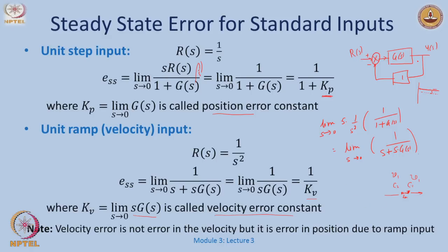Similarly, if I say give me a temperature of 24 degrees, and I just go to 23, the steady state error here is 1. I am just tracking a position, I just want to go to 24. However, if I say keep on increasing my temperature profile with time in this way, say it increases as 1 times T, this is my T and this is my reference temperature, with time it just keeps on increasing. I start from here and I will just be here. If this has to increase constantly with T, I will always be behind by say 1 degree. So at T equal to 50, I might just be at 49, and at T equal to 100, I might just be at 99. So it is just the difference in the position, not really the rate of my car here or the rate of change of temperature here.